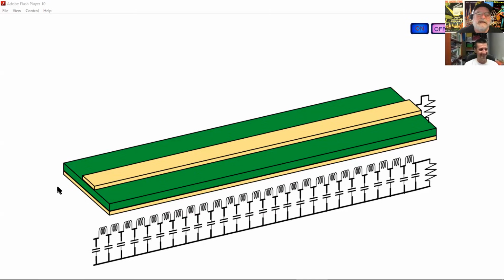That's not what a signal is going to look like as it's propagating down. Instead, when we launch 20 milliamps into the transmission line, it doesn't have to go all the way down and then come back to come out. Because what happens if this is an open over here? How does the return current get from the signal to the return? What if it's a 50 ohm, or what if it's some other resistance? How does that return current get to the bottom conductor and come out?